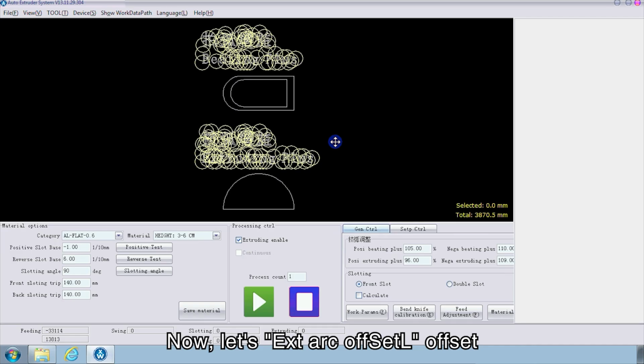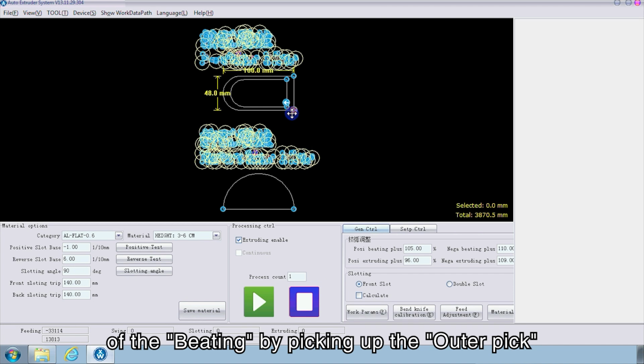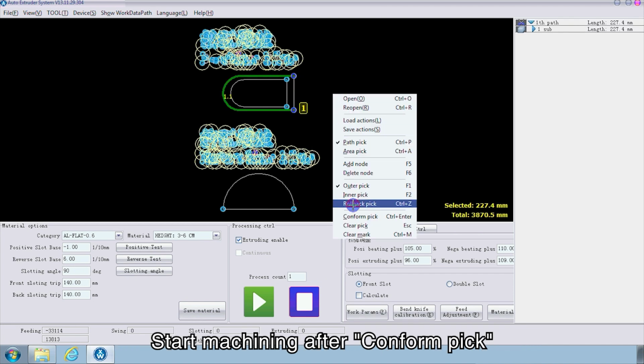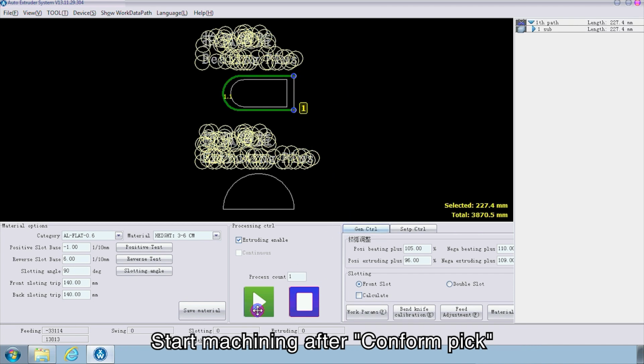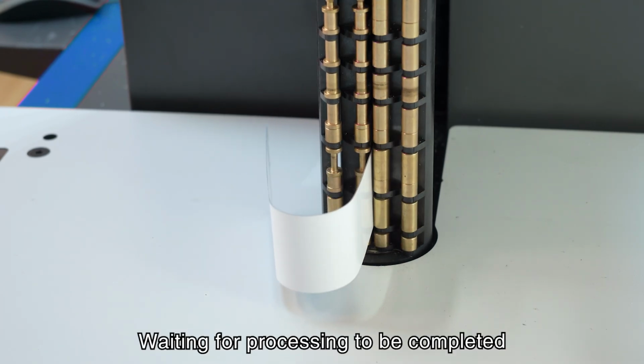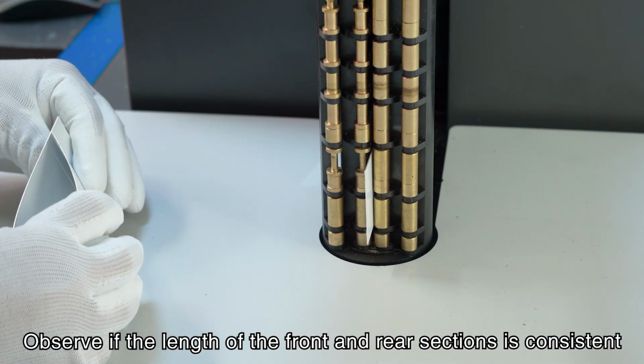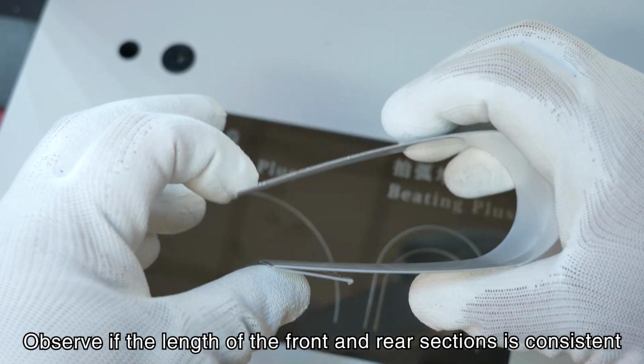Now, let's check the arc offset. Pick up the external shape of the beading by picking up the outer peak. Start processing after Confirm Peak. Waiting for processing to be completed. Observe if the length of the front and rear sections is consistent.